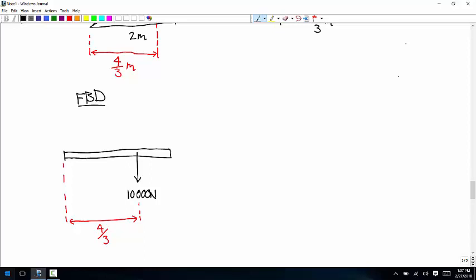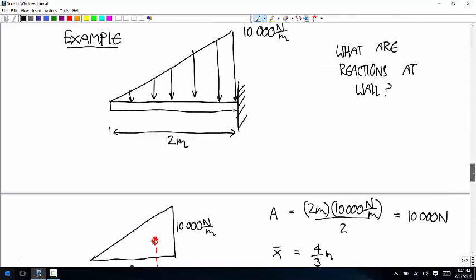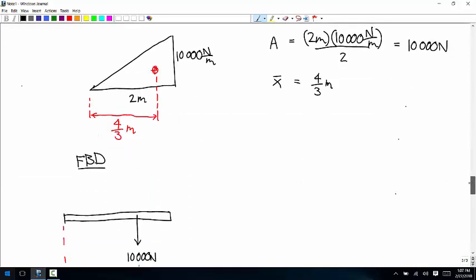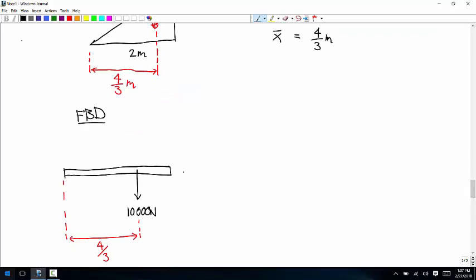And then the only other loads are the reactions at the wall. So with a fixed joint like this, what are the reactions? That's right. This is in 2D. A fixed joint doesn't allow any degrees of freedom. So you need 2 components of force and 1 component of couple. Okay, so we have an unknown force vector. I'll call that R. And we have an unknown couple. I'll call that reaction moment, MR.